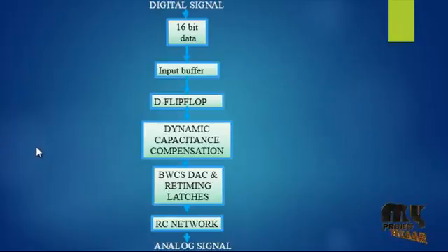A buffer is an amplifier that provides an interface between mismatched circuit elements. It is a unity gain amplifier packaged in an integrated circuit. Its function is to provide sufficient drive capability to pass signals or data bits along to a succeeding stage. Voltage buffers increase available current for low impedance inputs while retaining the voltage level. Current buffers do just the opposite, keeping the current the same while driving high impedance inputs at higher voltage levels. Next, the output of the buffer is fed into the flip-flop.